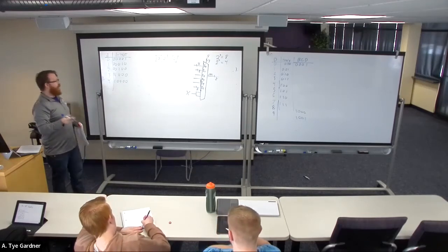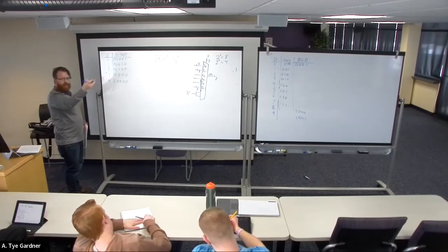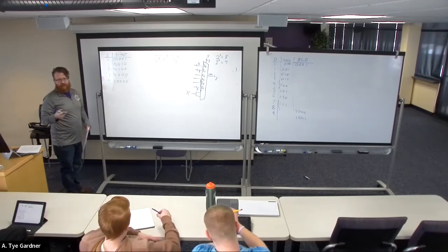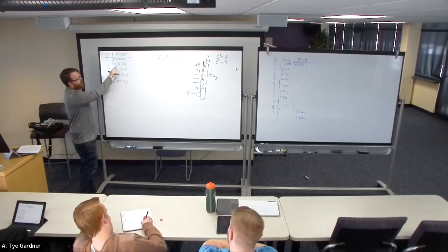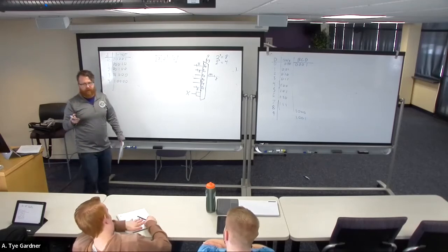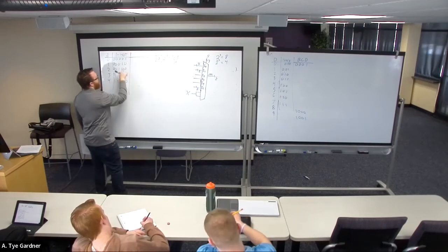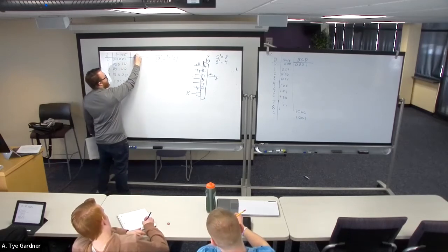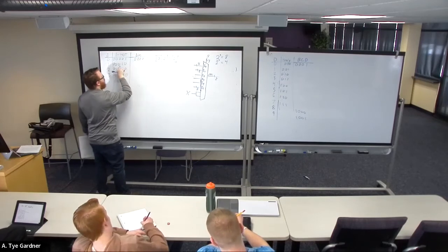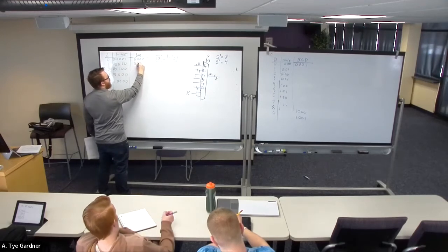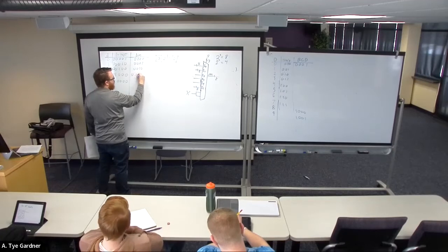It is. And there's this kind of implication if I wanted to convert between one hot and binary, I can do that, right? I could build a one hot encoder, and it would be really annoying to do it with this many, but with the 4 options. So let's say I had one hot and I wanted to convert to binary. Well, these are my inputs and my outputs. And my decimals are 0, 1, 2, 3, and the binary is 0 0, 0 1, 1 0, 1 1.